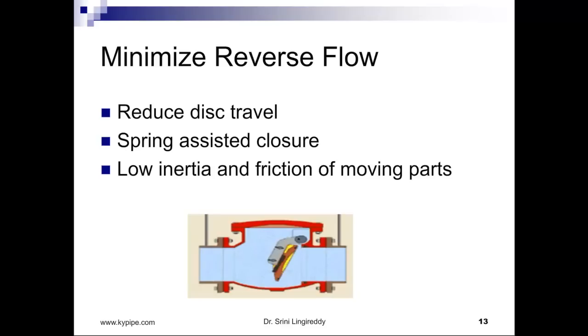But the problem with this is it is obstructing the flow. If you keep the disc in this position for steady state condition, it would be obstructing the flow, creating more head loss, and the check valve may come into operation once in a day or once in a year, depending on what type of system we are working with and how frequently we turn the pumps off or have a pump trip condition. Whereas with the check valve, the disc would stay in its position all the time the pipeline is operating. That means more energy loss. Okay, so that's the trade-off.